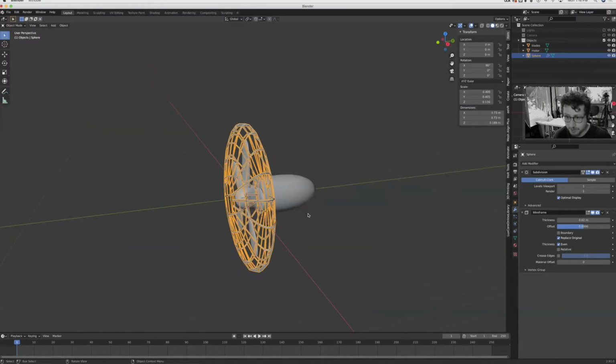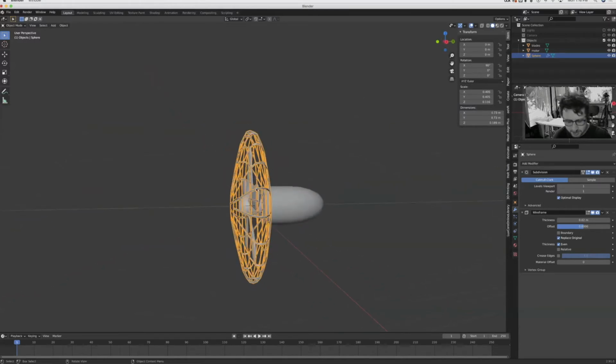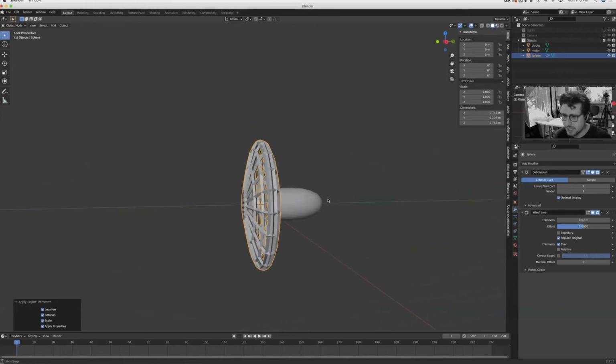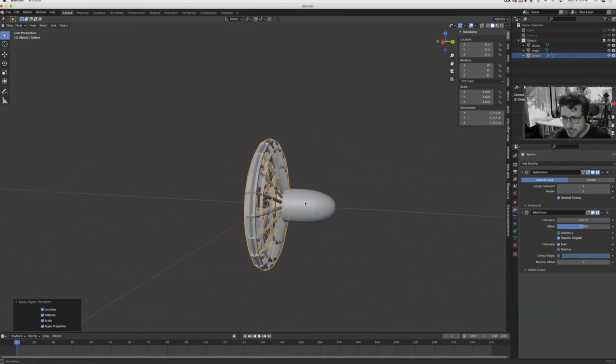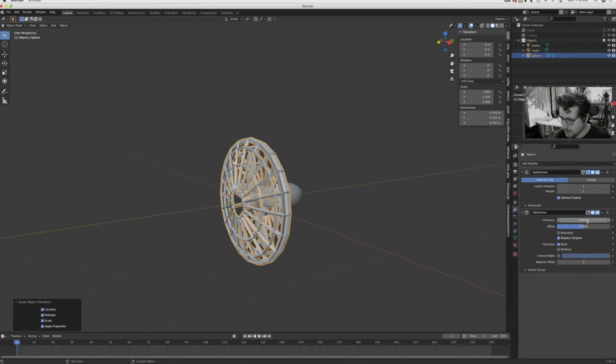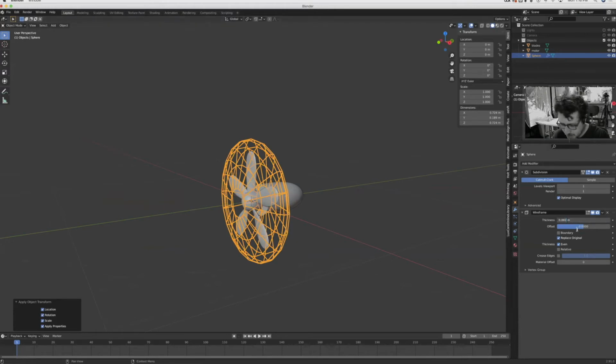So you can see our edges are kind of thicker from some dimensions than others. That's because we need to apply our scale and position. So I'll press Command A, and I'll apply all transforms. And now my frame looks way too thick. That's okay, because we have a thickness setting here. We can maybe just add a 0 into that. Maybe we'll make it 0.05. Or we can just scroll on it until it looks good, which seems to be a better approach.